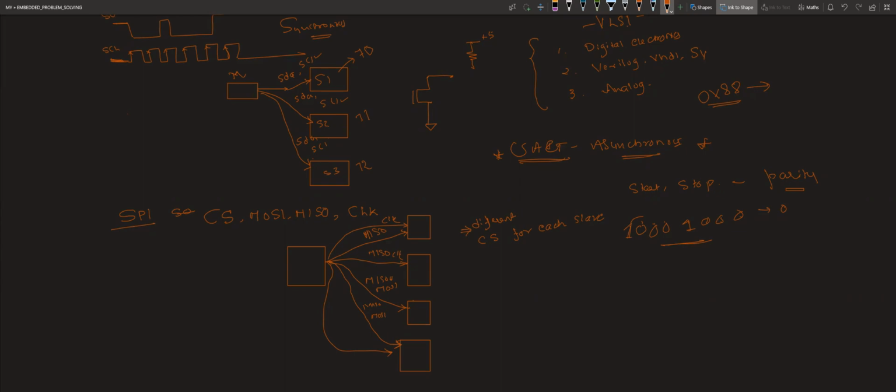External data can be pushed only through the MOVX command. That's correct, right? So MOVX is basically for the external memory. Fine. So if it is the internal memory, which one do we use?